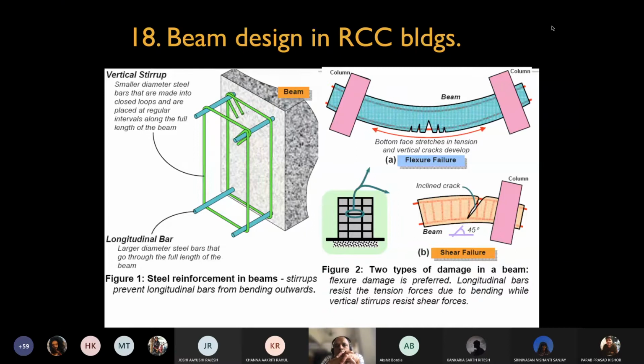That is, to be able to bend, to have flexibility, and to absorb some of the damage to an extent that life is not lost and the building is still able to stand on its own while taking some cracks. Many structural engineers now design precisely knowing that if there is an earthquake of this magnitude, this is where we want the failure to happen and not in that position. So in a building, it is important to have flexural failures and not shear failures.